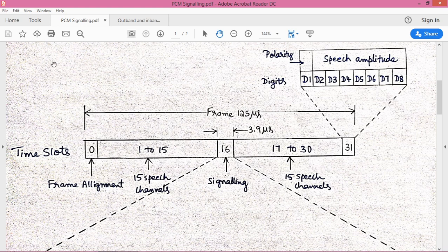So instead of sending only one sample signal within this 125 microseconds, we make use of other signal samples and pass them through the channel. So that is what space switch is about. We have already discussed how space switch and time switch operate. So we know how PCM frames are formed to transfer multiplexed data, or to transfer different signals over a particular channel.